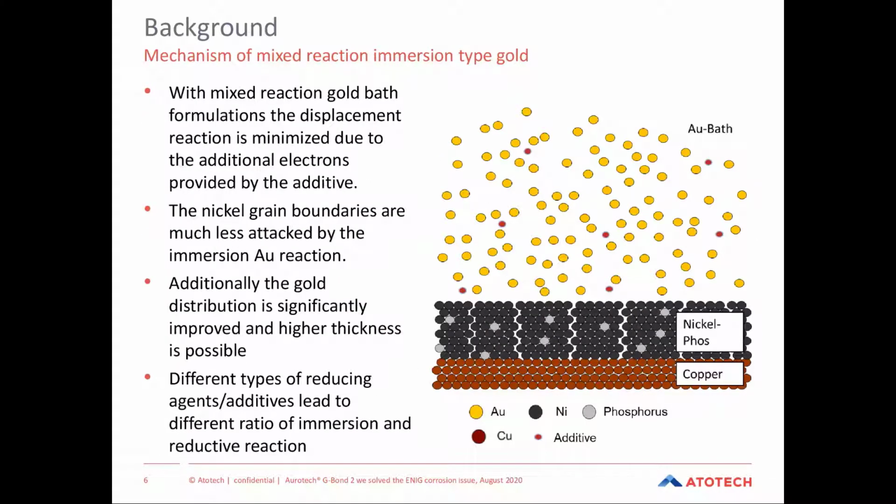With the latest state of the art mixed reaction immersion type of gold, we have a combination. So we have additives inside which already provide some reducing properties, and with that can provide some additional electrons and reduce the nickel attack.